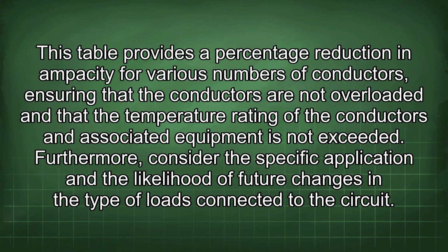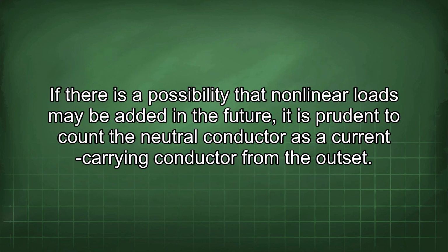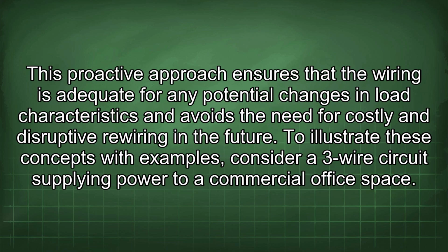Furthermore, consider the specific application and the likelihood of future changes in the type of loads connected to the circuit. If there is a possibility that nonlinear loads may be added in the future, it is prudent to count the neutral conductor as a current-carrying conductor from the outset. This proactive approach ensures that the wiring is adequate for any potential changes in load characteristics and avoids the need for costly and disruptive rewiring in the future.